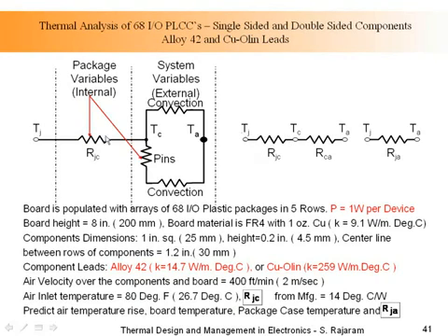So there are two resistances, a junction to case. This came from the manufacturer. And now our trick is we need to be able to determine what this case to ambient is. If you combine the two, we define what is called a junction to ambient resistance, and this is also a parameter that some manufacturers will give you. So this is normally how we look at an analysis from a design perspective.